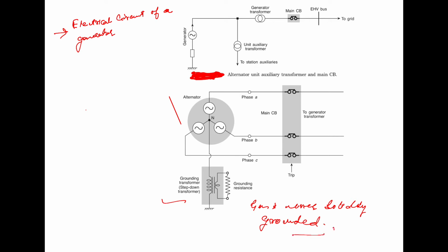Solidly grounded means that the resistance is equal to 0. If it were so, the single line to ground fault current would be dangerously very high.